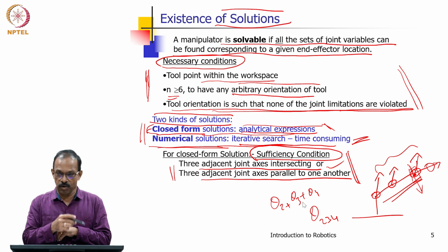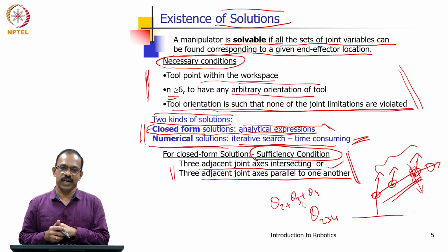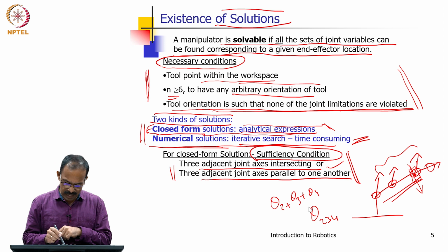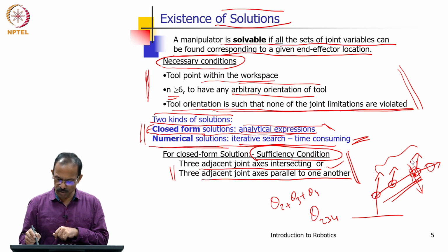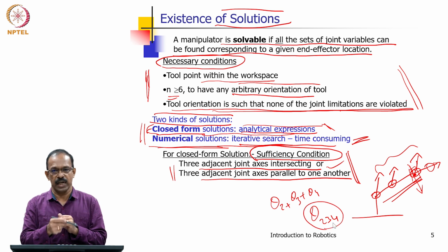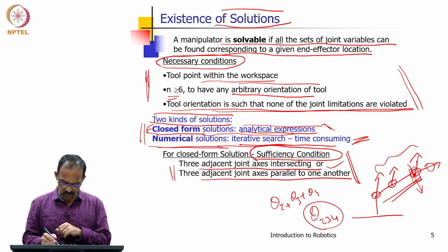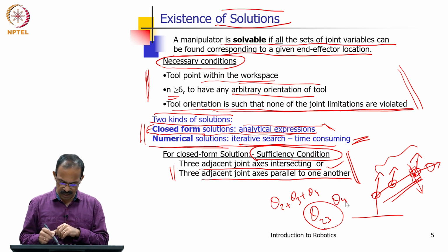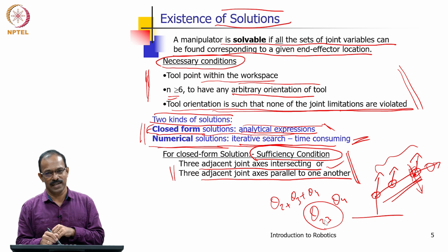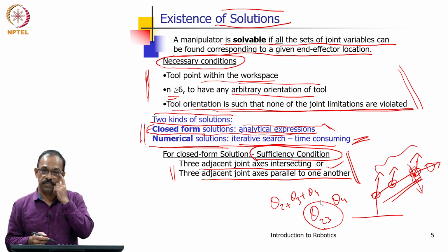Okay, so that is the form it was coming in, the arm matrix or the arm equation, and that is the reason why we need to have this kind of parallel axis, so that you will be getting it in this format. So, it can actually be solved. If they are not this way, then you will be getting theta 2, theta 3 and then theta 4 as another one. Then you have to solve for theta 2, 3 and 4 separately. That actually leads to problems in the solution.